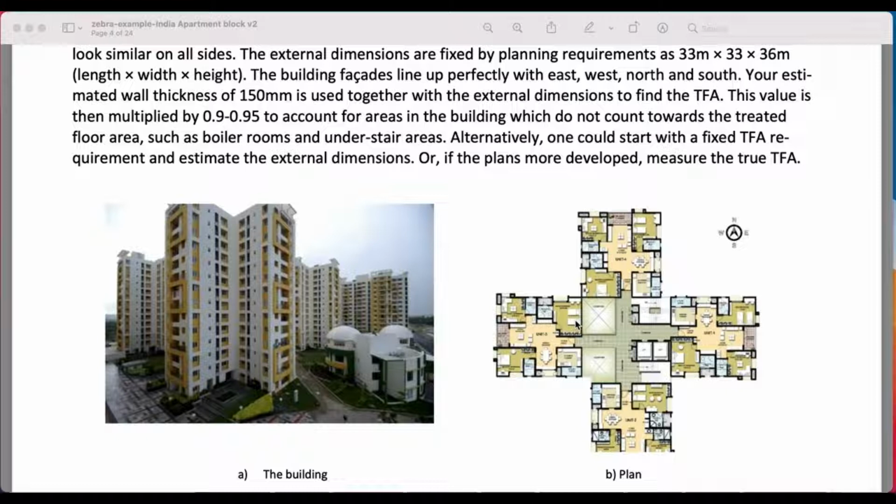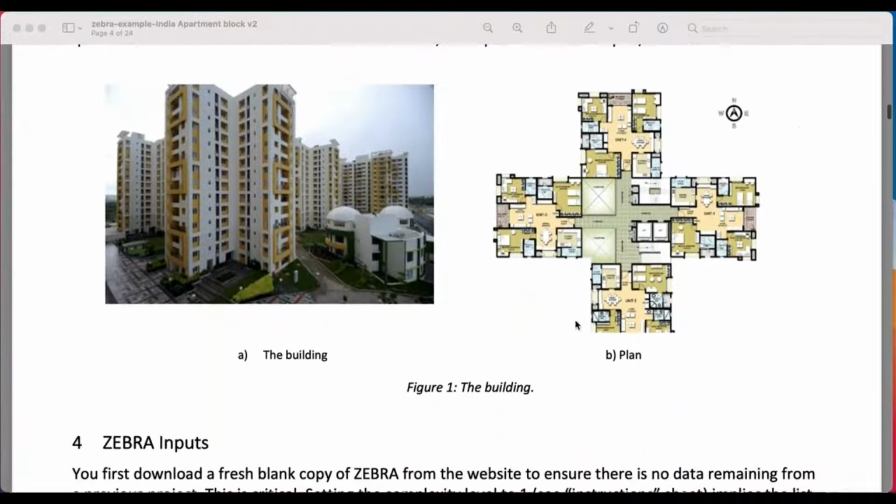And that's called parametric modeling, when we take 2 possibilities of a situation, we're just not quite sure how to represent it. So for example, we might not know exactly how people are going to ventilate the accommodation. So we're going to repeat the modeling in Zebra with option A and option B, just to make sure that we understand how the energy use or other parameters change as a function of that input parameter. And it's a way to add a lot of robustness to your modeling.